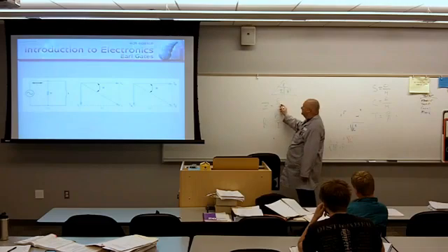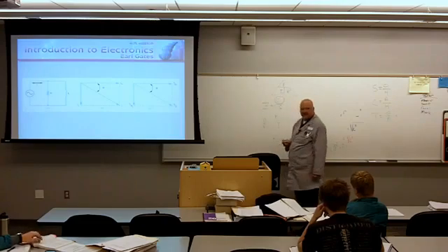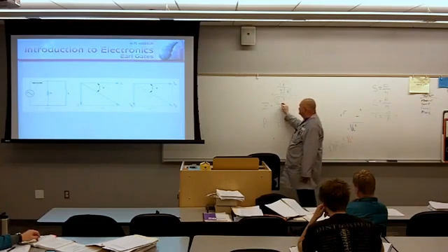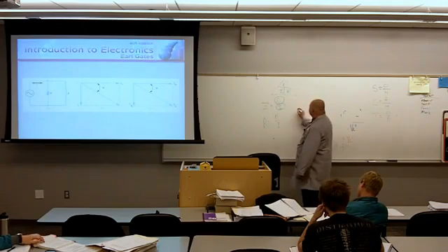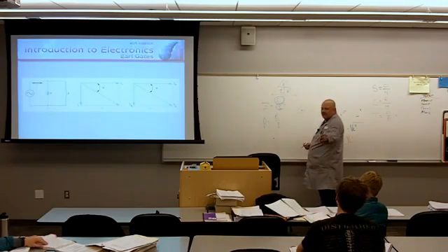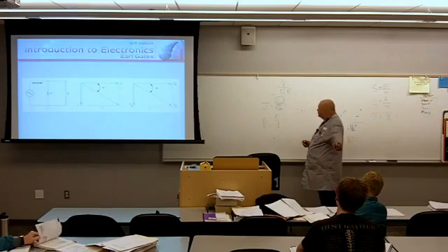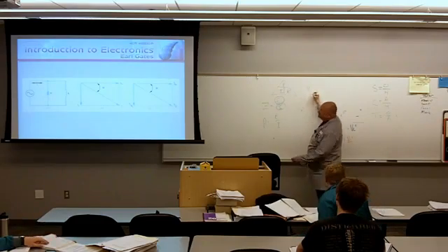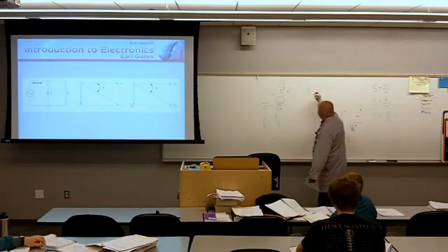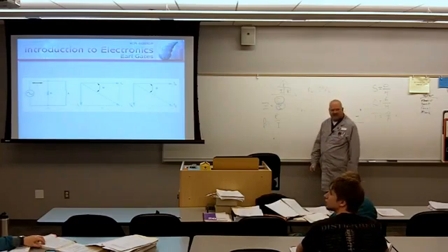The good news is this should be an easy one to get, because it's the same voltage across the parallel network. This is kind of engraved in stone in a parallel circuit. How am I going to get this number? You have to find reactance. No, you don't have to find reactance. That's the whole thing. I don't recommend you do that. Good question, though. If this has an inductor in it, X sub L equals 2 pi FL. You just calculated your reactance.